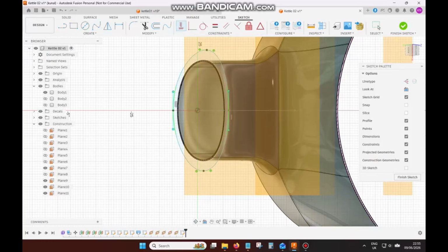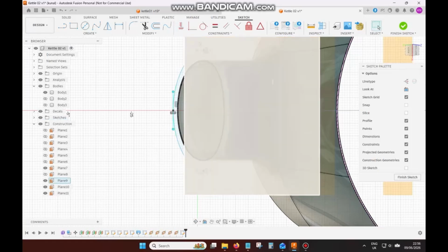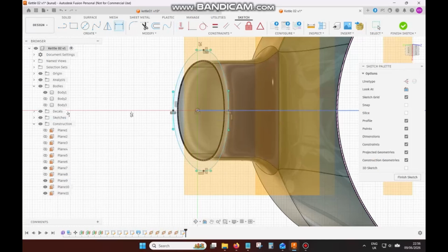I mean, I think on this handle, it's a little fatter at the top and it tapers down to something thinner at the bottom. So that's what I'm doing here. Now, on each of these profiles, I'm using a spline with 4 points, and I'm going to try and make this as symmetrical as possible. At each of those points, I'm using the vertical horizontal tool in the Fusion sketch section to make each of those spline handles vertical and/or horizontal.